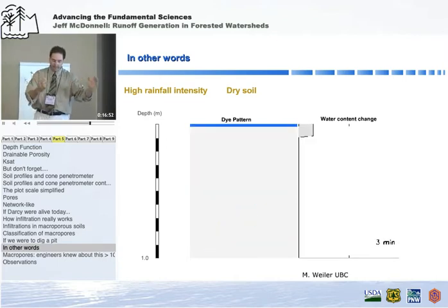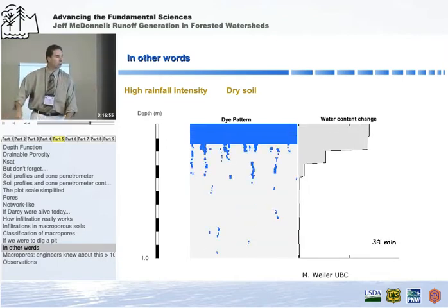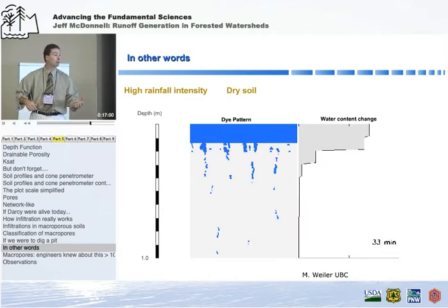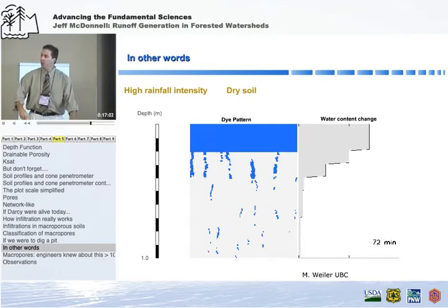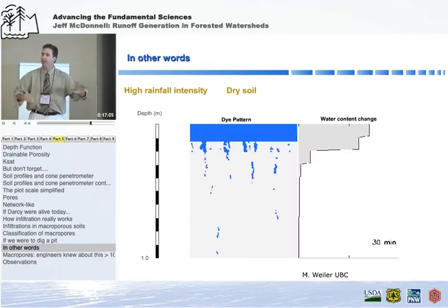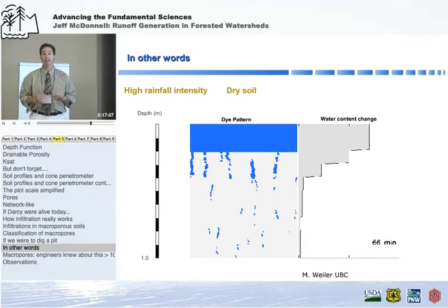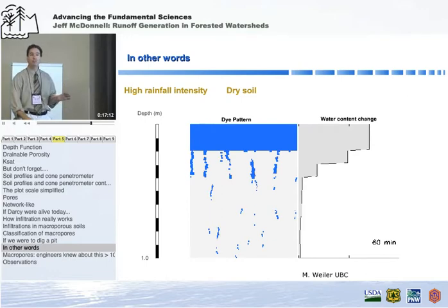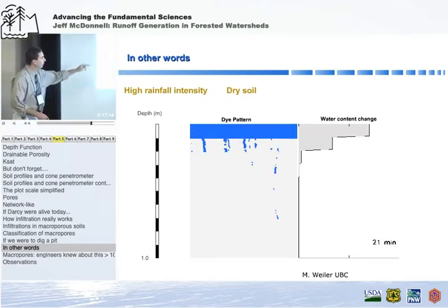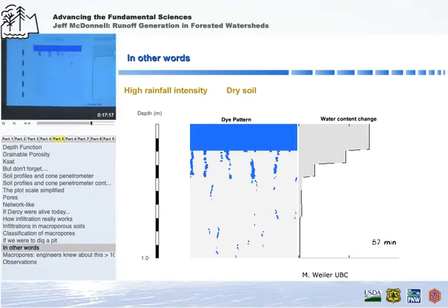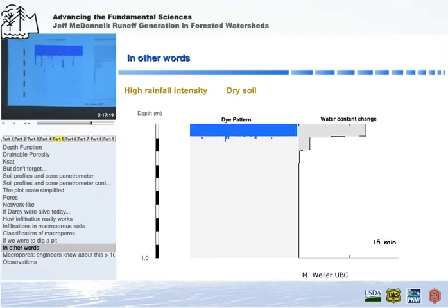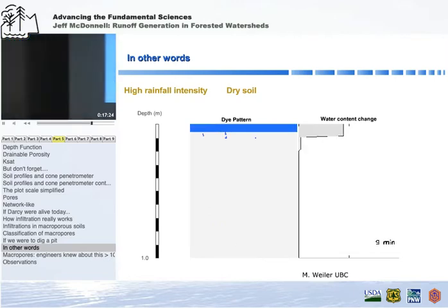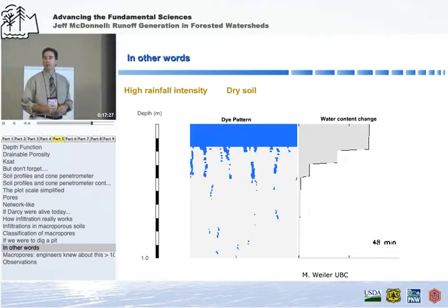They're often excavated down to 20 feet, and they throw in the low-level radioactive stuff. It's often lacustrine clay, low permeability material. Fill it back up with that low permeability material, tamp it back down again, and leave it for 1,000 years. That's fine, because it's a very dry environment, and the regional water table's perhaps hundreds of feet down. But over time, and with vegetation development, because the vegetation is often the key driver of macroporosity, these are some of the issues that people are concerned about.